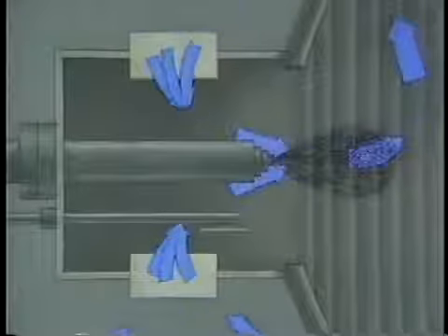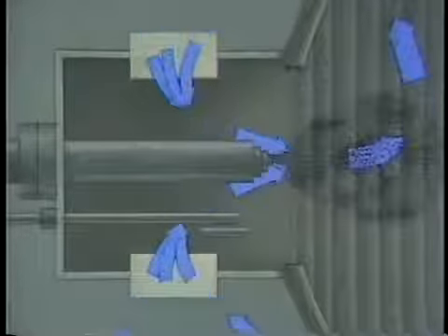The air and fuel form a combustible mixture. The mixture accumulates in the boiler as more fuel and air are supplied. If the igniter suddenly begins sparking, it will ignite this abnormally large mixture. The result is an explosion.